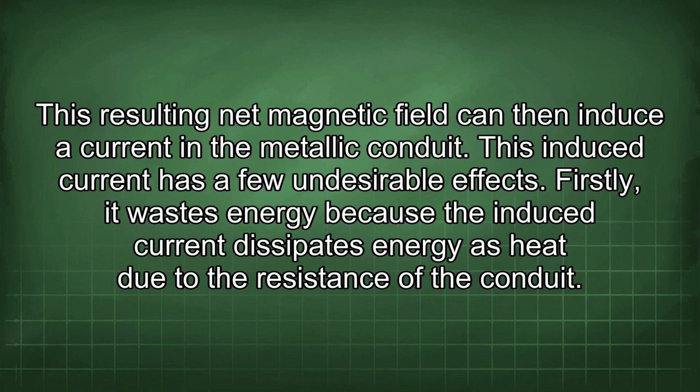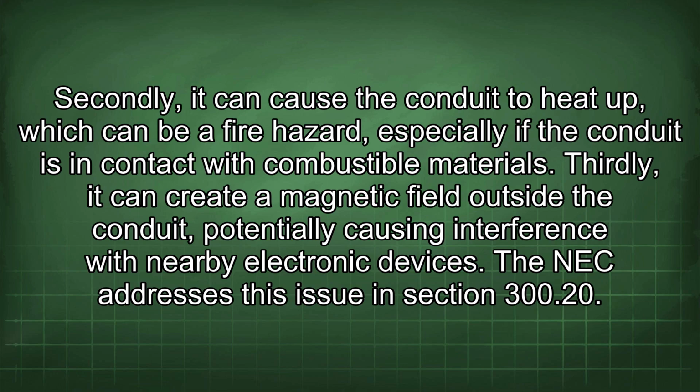This induced current has a few undesirable effects. Firstly, it wastes energy because the induced current dissipates energy as heat due to the resistance of the conduit. Secondly, it can cause the conduit to heat up, which can be a fire hazard, especially if the conduit is in contact with combustible materials. Thirdly, it can create a magnetic field outside the conduit, potentially causing interference with nearby electronic devices.